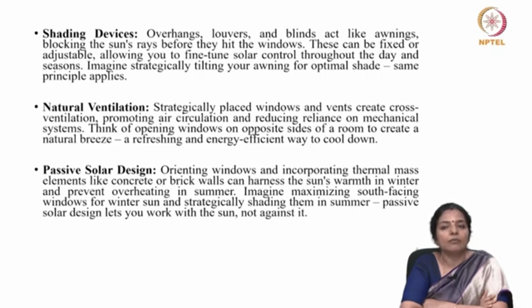Orienting the building's windows and incorporating thermal mass elements can harness the sun's warmth in winter, and it can prevent overheating in summer. At the same time, when you are designing for a hot humid climate, you must consider that there should be adequate ventilation, and therefore openings and opening sizes along with their location become an important criteria.